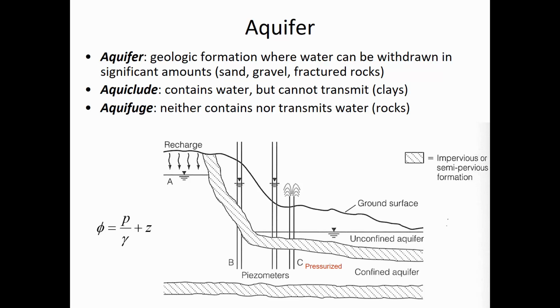The water's having to flow through the soil to get there, and so there's some losses similar to if it was flow through a pipe. Anytime there's water velocity, there's going to be energy losses. And since the ground level is higher than the water depth at B, then water isn't naturally going to be spurting out of that well. You'd still have to have some sort of a pump to get the water out of that well.